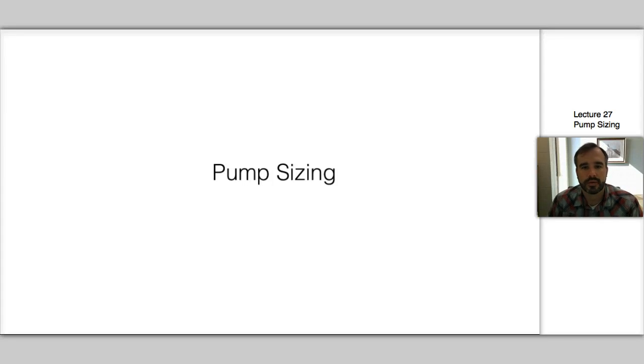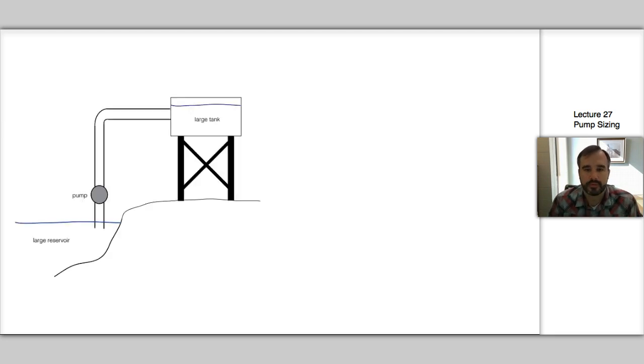Okay, so the last topic I want to cover in the conservation of energy is pump and turbine sizing. I'm going to go specifically over pump sizing, and turbines really work kind of the same way, it's just in the reverse order. So when you want to size a pump, you typically have some sort of engineering problem like we have set up here, where for this example we have a large reservoir, we have some pump that's piped with some piping system that's pumping water to a large tank, say, that's elevated, so say a water tower for a city water supply.